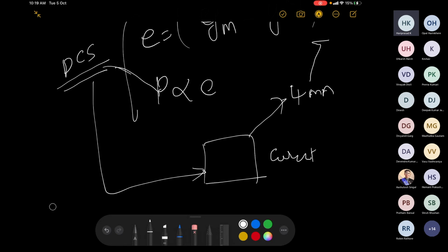Based on this error, your controller output is basically what your DCS calculates. Now, if this controller output gives you 20 milliamps, which is the other extreme, the DCS would trigger a signal, and the source should give an output corresponding to 20 milliamps. So this is the way it is finally implemented in the field. So don't think that this is an easy exercise. That's why I went into every detail and explained it.